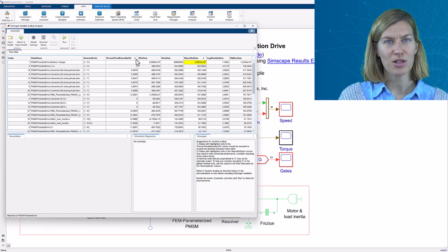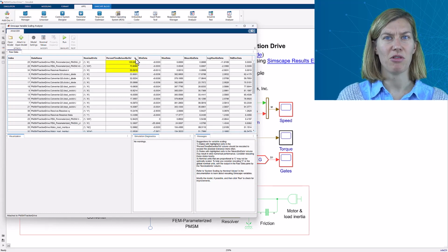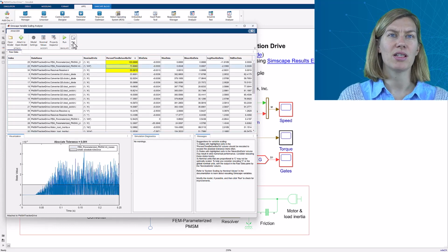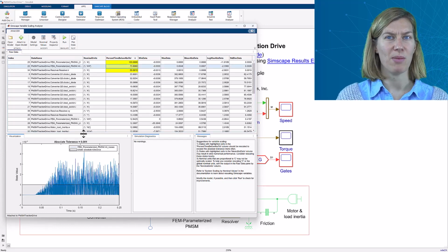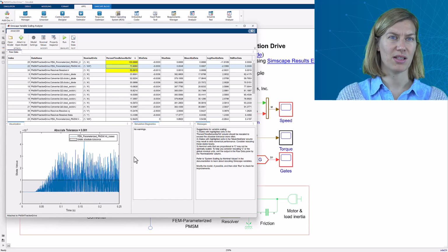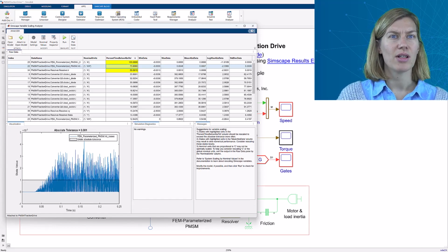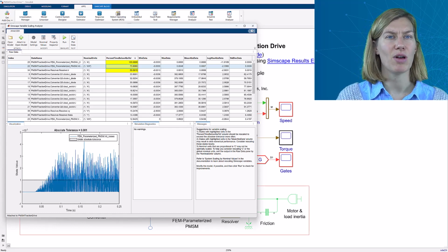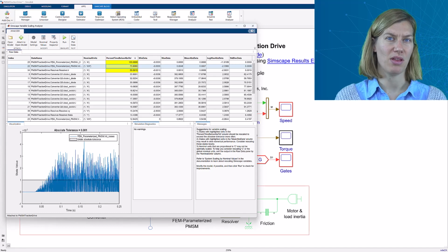Use the plot option to create a visualization of states with respect to their absolute tolerance value. This will plot the state value and display it together with a gray band indicating the tolerance limits. This could help you to decide if this is representing noise or if scaling could be helpful to lower the percentage time the value spends within the tolerance band.